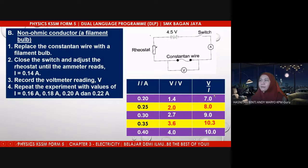So this is the ratio that we get. The first ratio, V over I, from the first reading is 7. The second is 8, the third is 9, the fourth reading is 10.3, and the fifth reading is 10. So you can see that the ratio is increasing. It is not consistent like the ratio shown by the ohmic conductor.